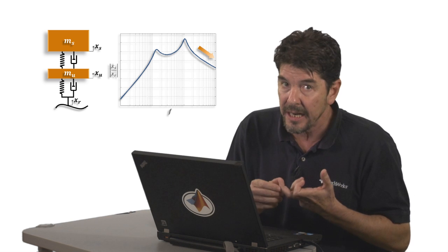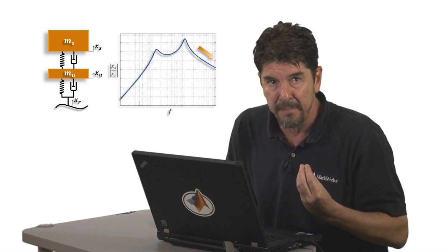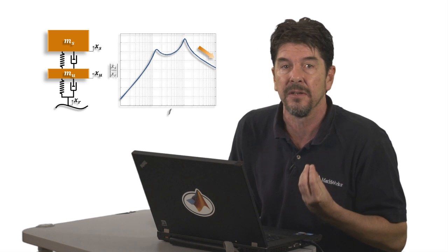Anyways, the point I'm trying to make with all of this is that control engineers need to go through the trouble of analyzing things in the frequency domain because it adds a very important dimension to the observations of our system responses. I like to think that looking at systems exclusively in the time domain, which can feel more natural to us, is analogous to a mechanical designer trying to infer the shape of a three-dimensional part by looking at just a single two-dimensional drawing of one of its sides.